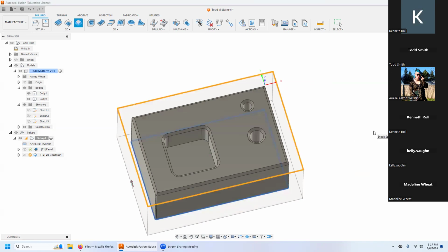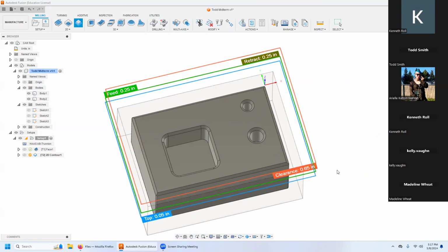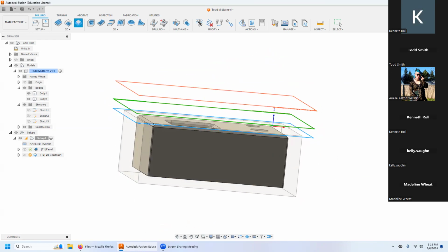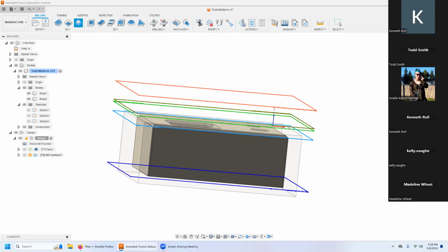You know, let's try it. Let's add it in, see if it does anything good for us this time. Sure, why not? No tabs, dress machining, tool orientation, we're good. Heights. Okay. I'm going to go, well, selected contour, because I grabbed the bottom of the part, would do fine. Or model bottom, either way. I like model bottom because then I can see this blue line and have surprises. There are other very good reasons for picking other stuff. I don't need stock top because I've already faced, so I'm going to go to model top.